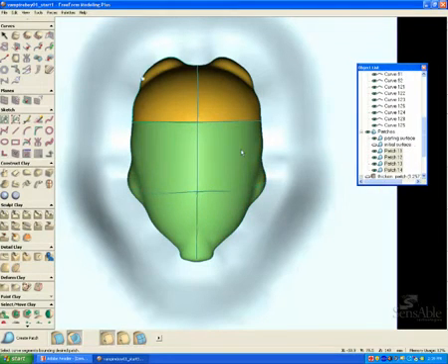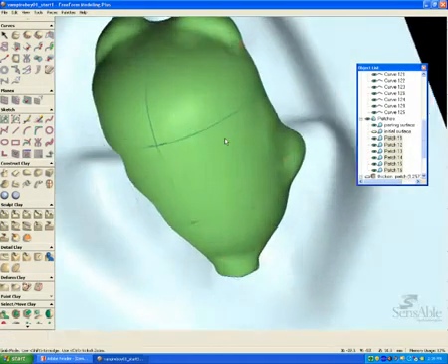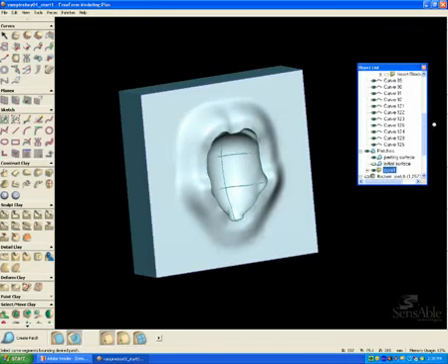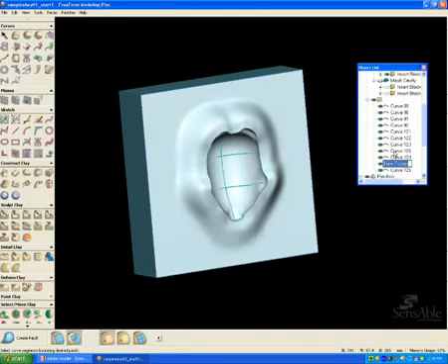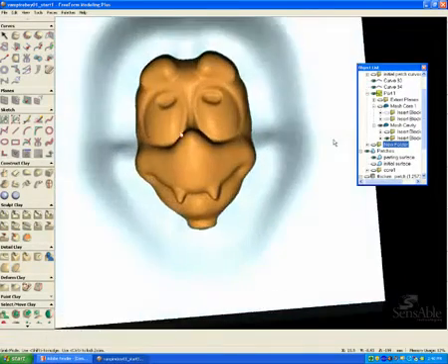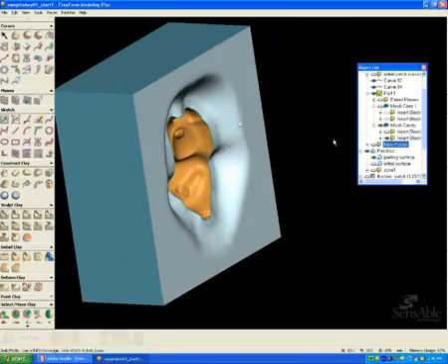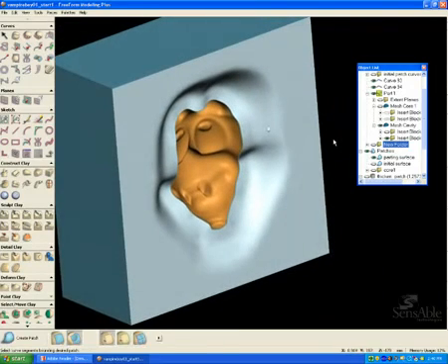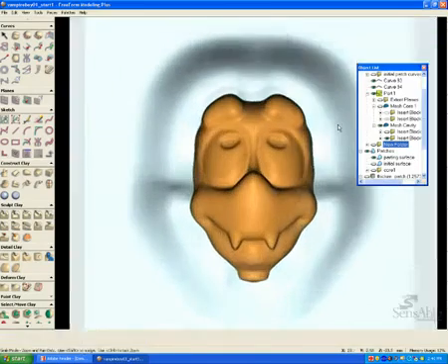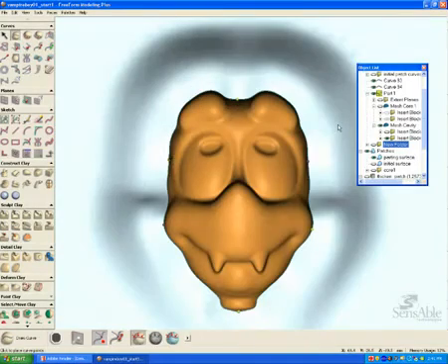So you can see I'm selecting each of these curves singularly and creating those green patches, which are connected to the parting surface at that edge, as you can see around the edge of where the actual void is. And now I have that one parting surface and the void for that one side. Now I'm doing the same thing, turning on the other mesh cavity and the other insert block. This is all organized in our object window. You can go through and turn different pieces on and off very easily.